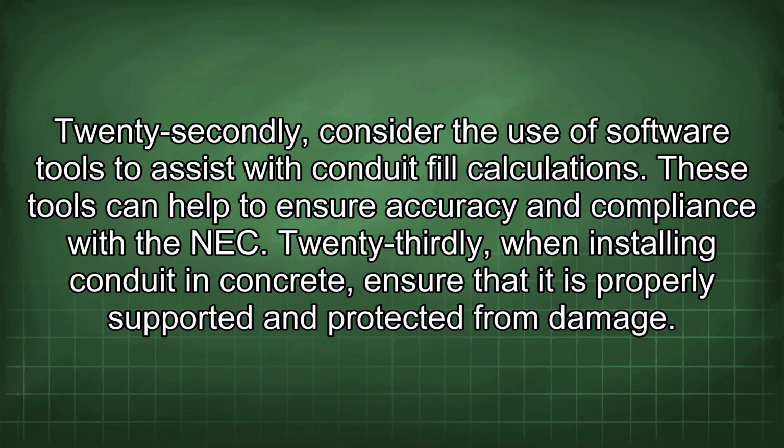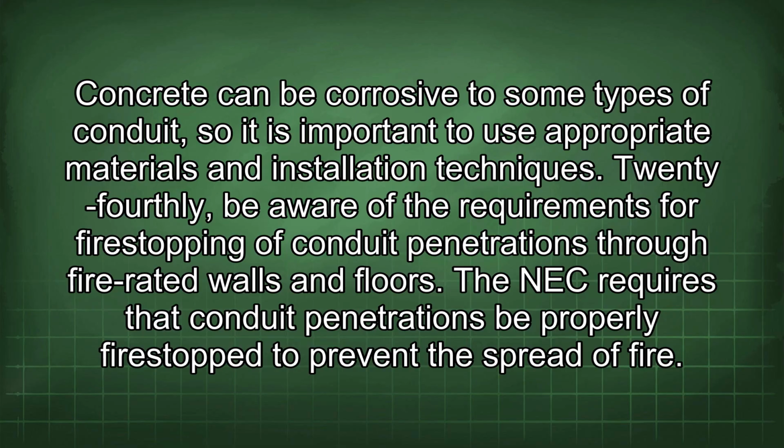23rdly, when installing conduit in concrete, ensure that it is properly supported and protected from damage. Concrete can be corrosive to some types of conduit, so it is important to use appropriate materials and installation techniques. 24thly, be aware of the requirements for fire stopping of conduit penetrations through fire-rated walls and floors. The NEC requires that conduit penetrations be properly fire stopped to prevent the spread of fire.